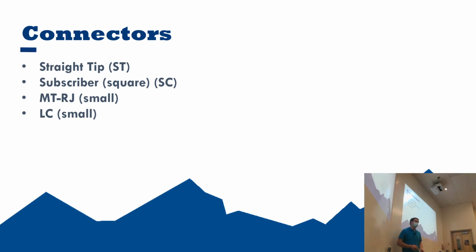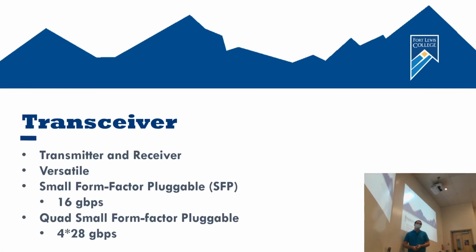In general, they're going to be compatible. Like you can see, we have different connectors on the same cable. So we're going to talk a little bit about those sort of exchanges. But if you're going across the same medium, you don't have to change the whole cable to change the end. You can basically do it on the same. So if I were having a copper cable, and let's say it were coaxial, one end could be BNC, the other could be an F connector, F-type connector. It doesn't really matter because it's the same type of signal. It's only whenever you change the type of signal that you need to convert it to something.